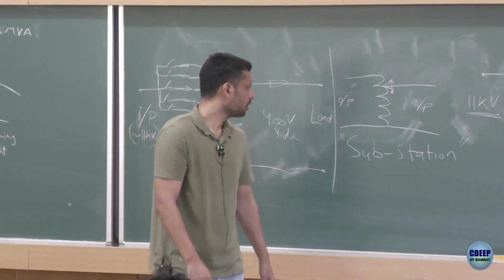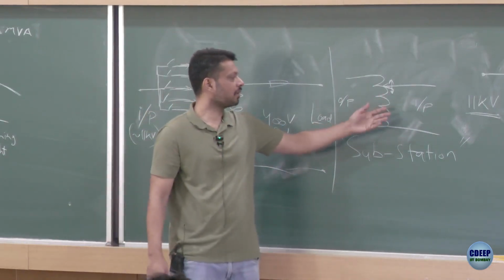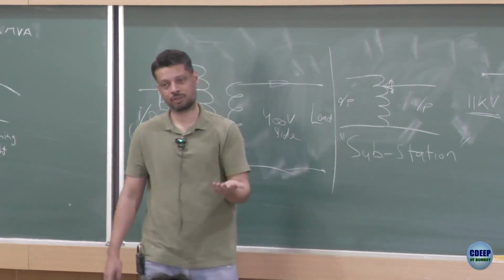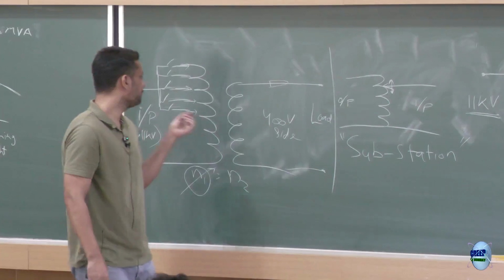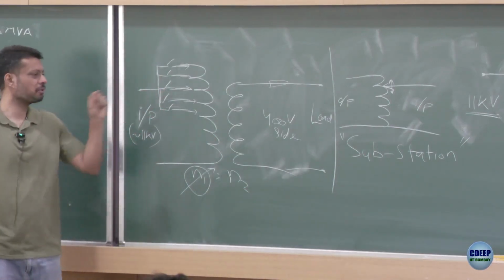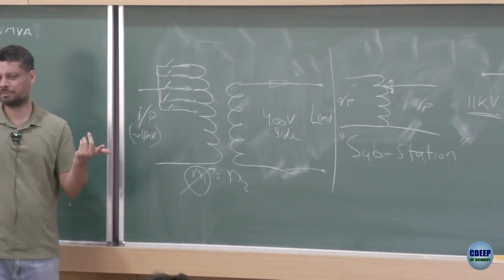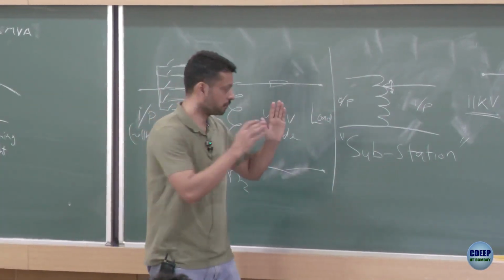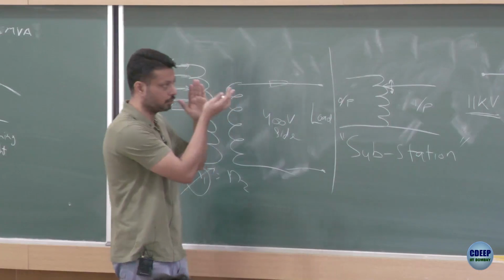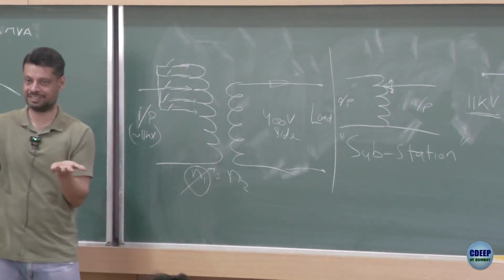Oh, no. So, having one auto transformer extra is of course costly. You anyways have a transformer, you build a few more extra things, just take out a few more taps from the same transformer. Why do you want to have one more auto transformer? So, including it in the main transformer is of course much cheaper.